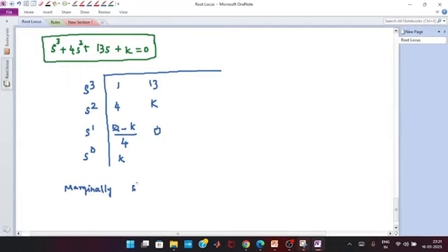When the system is marginally stable, you have the concept of ROZ. What is the meaning of ROZ? That is nothing but row of zeros. At which place will the row of zeros always exist, odd power s or even power s?